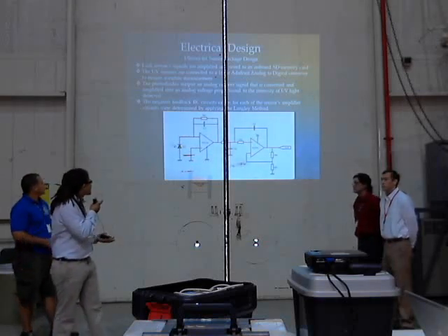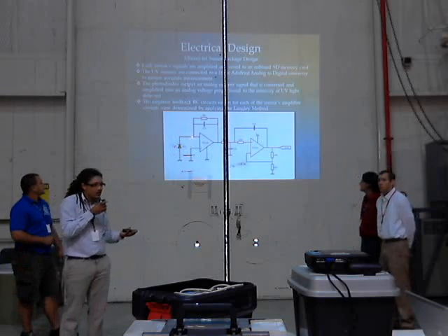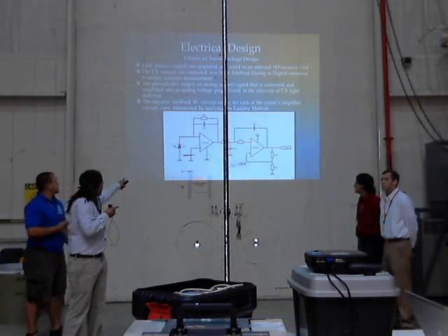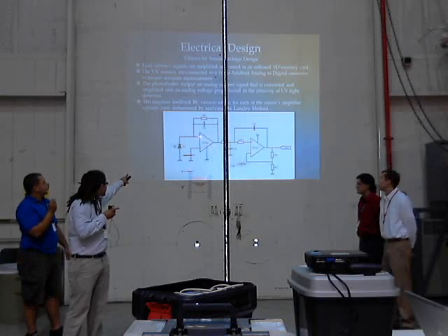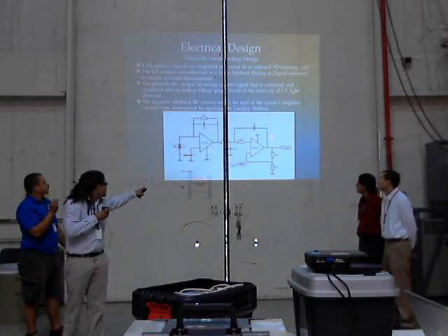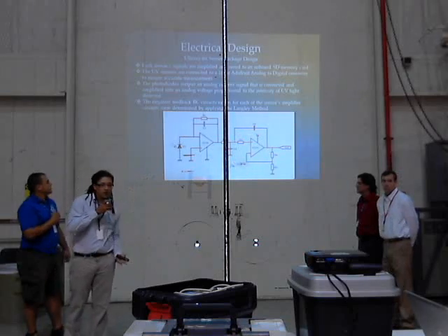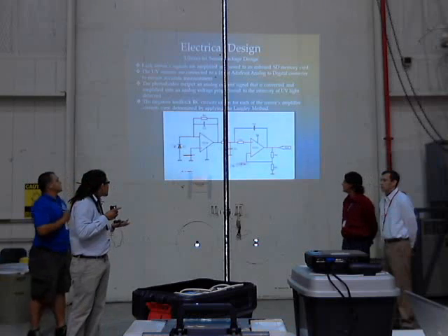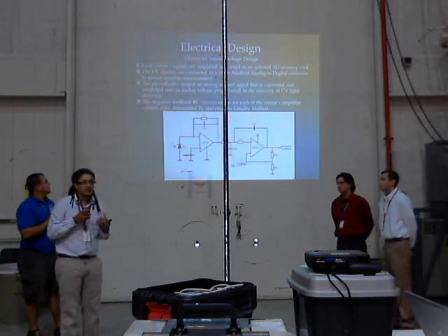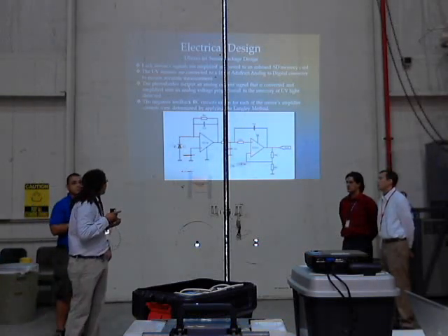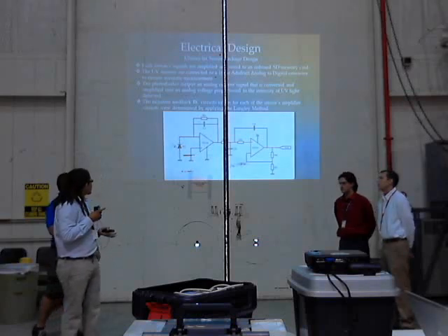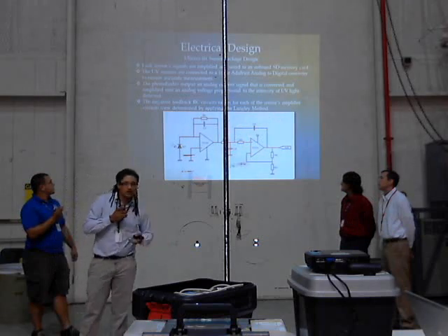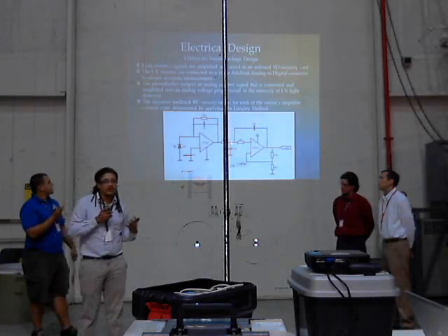The photodiodes output an analog current, and we convert that into a voltage. We've got a preamp here conditioning the circuit, and then a Butterworth filter, which is a low-pass filter to cancel out noise, so that we can get just the data that we want. The negative feedback circuits for each sensor, like we said, were determined by using the Langley method.